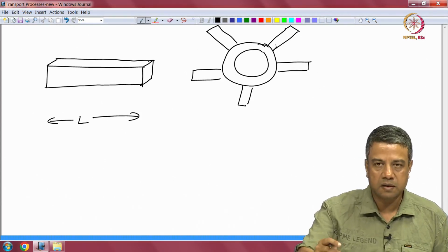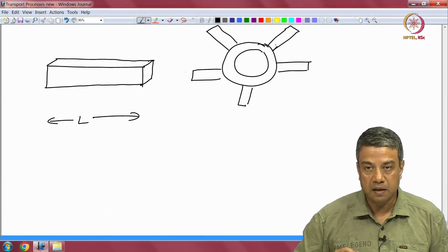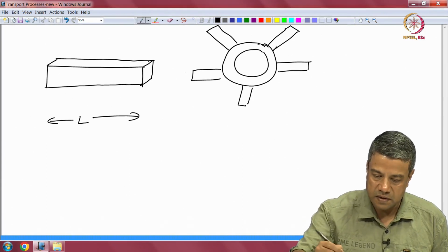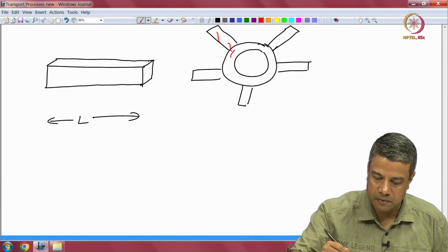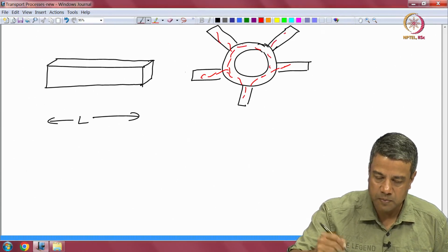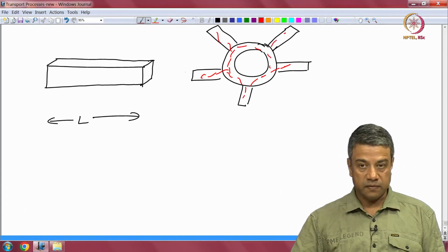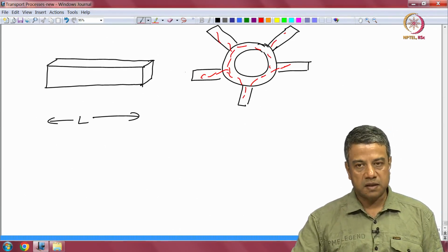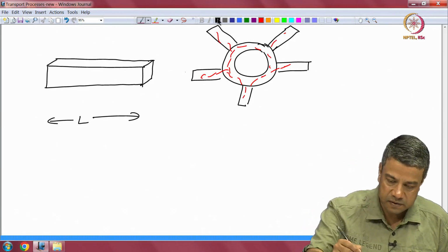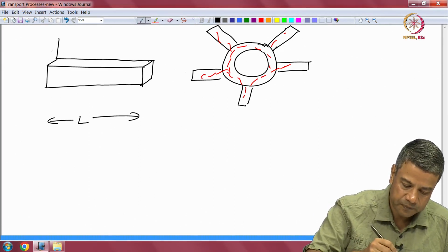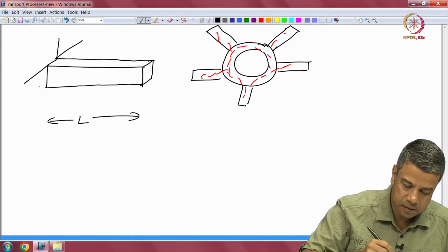So, if you have a metal tube with metal fins, the thermal conductivity is very large. So, virtually the temperature is the same everywhere, and by putting fins you have increased the area for heat transfer. So, the heat flux also increases. This is the kind of configuration that is observed. So, for example, typically you will have a tube on this side.